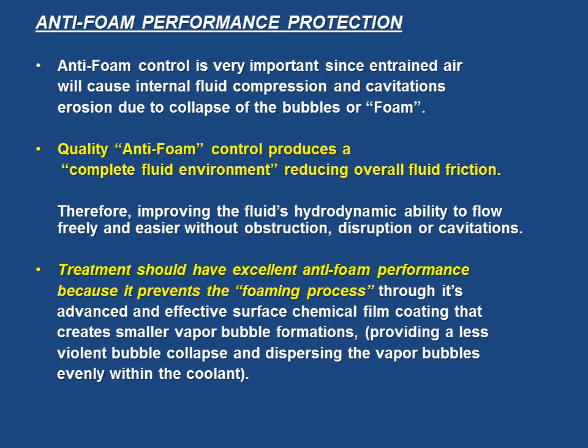And that is where improved chemical science comes in. You see, the treatment should have an excellent anti-foam performance because it prevents the foaming process through its advanced and effective surface chemical film coating that will create and encourage smaller vapor bubble formations, providing less violent bubble collapse and dispersing the vapor bubbles evenly within the coolant. Say, Clayton, you said that twice. I was trying to drive a point.